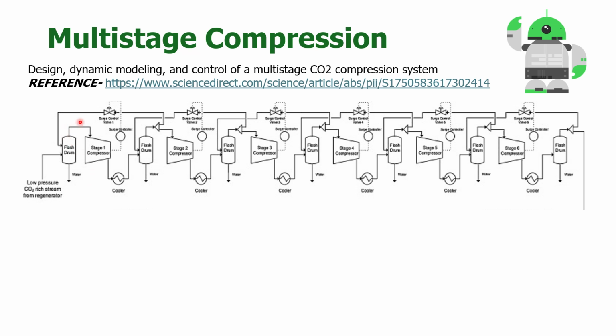It's just a random value and figure. So you'll be able to increase it to, let's say, 20 bar, and your gas temperature will also increase due to thermodynamics. Okay. And after you have this hot gas at the outlet of the compressor, it is not recommended at all to send it directly to the second stage compression, because the hot gas could cause some wear and loosening inside this rotating machine. That's why it's required to do interstage cooling. It is written mainly as cooler, but we mainly call it the interstage cooler.